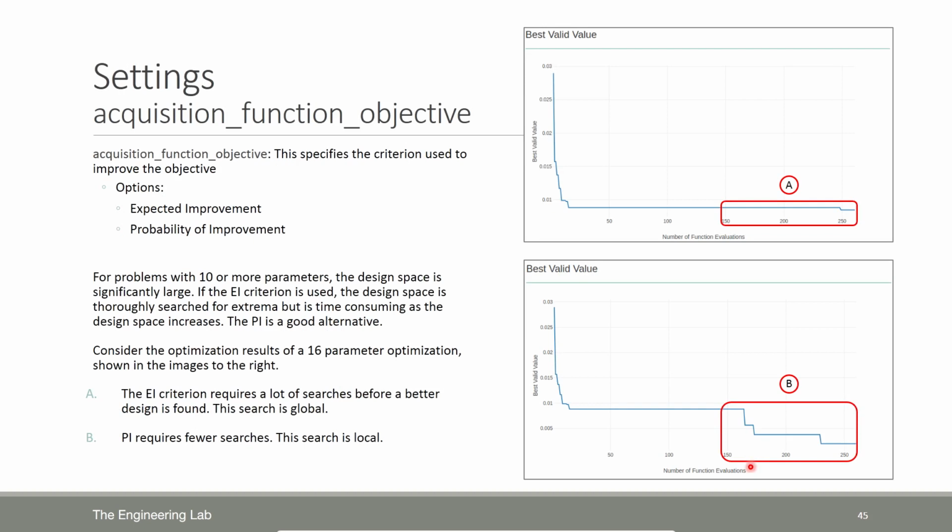One quick comment regarding the acquisition function. When I have tested the expected improvement criterion, it works well if you're dealing with 1 through 5 parameters or variables. It also works well in some cases if you work with 10 parameters. When you are working with, say, 15 or 20 parameters, expected improvement does work, but you're going to run Nastran or your black box function multiple times.